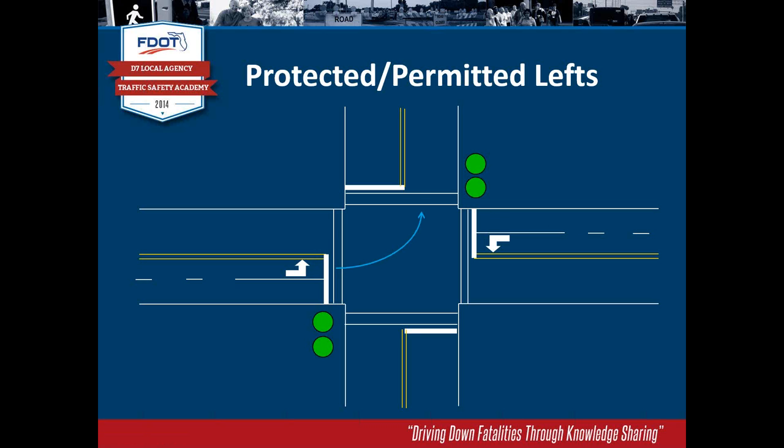Well, if you weren't paying attention, you could run into the pedestrian who's in the crosswalk crossing when he's still in his walk or in the flashing don't walk of his pedestrian crossing period, and serious consequences could result for that pedestrian. He's unprotected and it could be very serious for him. So that's one of the considerations you have to be thinking about if you're going to be implementing any permitted left turn operation at all.